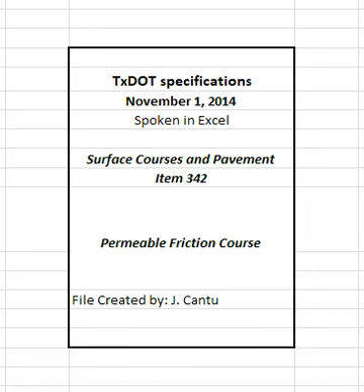4.4.2.2.2 Hamburg wheel and overlay testing. At the contractor's request, the department will perform the Hamburg wheel test on the laboratory mixture in accordance with Tex-242-F to verify compliance with the Hamburg wheel test requirement in Table 4. The department will perform the overlay test in accordance with Tex-248-F to verify compliance with the overlay test requirements in Table 4. The engineer will be allowed 10 working days to provide the contractor with Hamburg wheel and overlay test results on the laboratory mixture design.